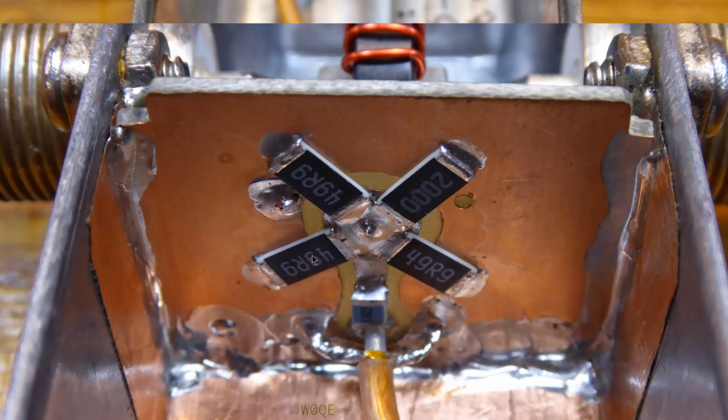And here are the resistors that comprise the resistors across this toroid. In my case, it was 15 point something ohms, 49.9, 49.9, 49.9. These give me like 16.67 ohms. In parallel with 200, gave me something like 15.4 something, which is very, very close.